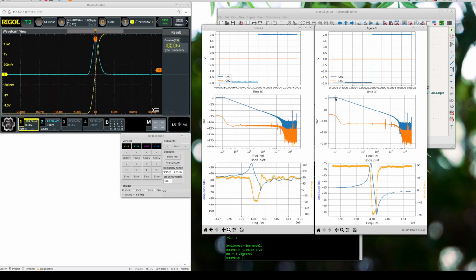But the advantage is that the frequency spectrum is very nice, because you only have one edge, and the frequency on the screen, which is where the FFT is taken from, is exactly in the middle of all the bins. So there is no ripple. I can also show that if I lower the time base.